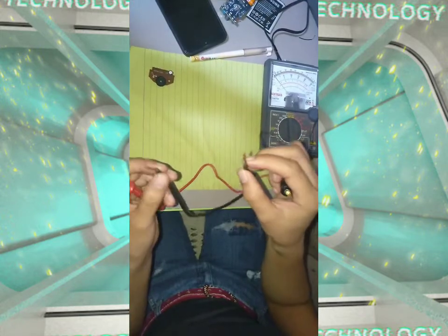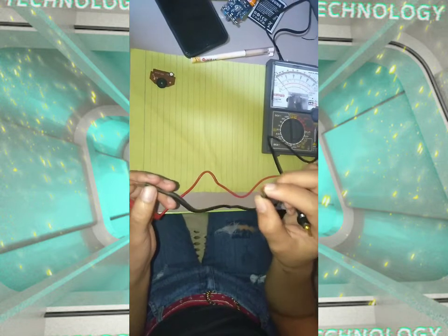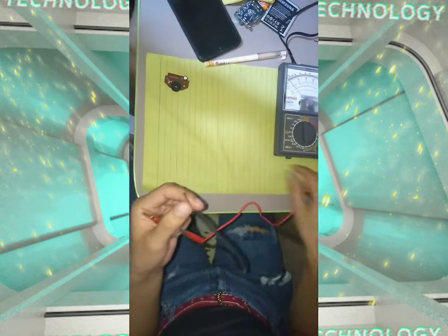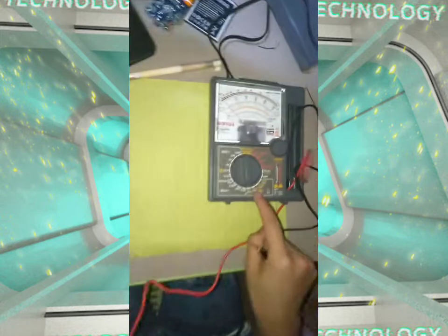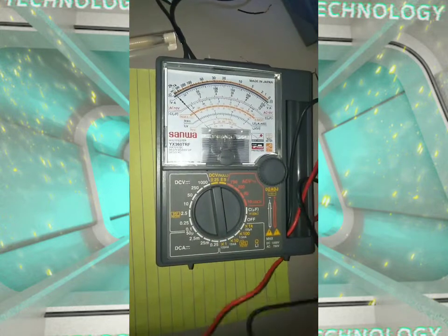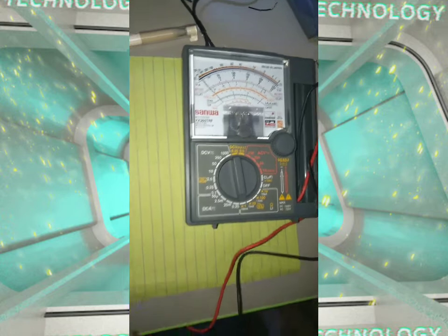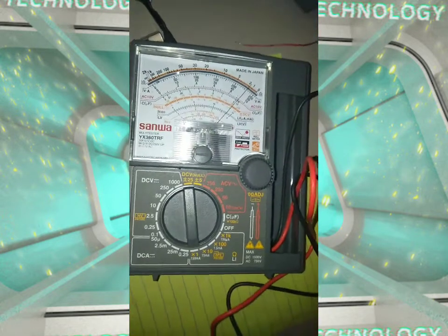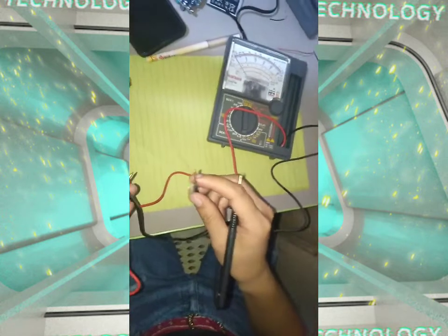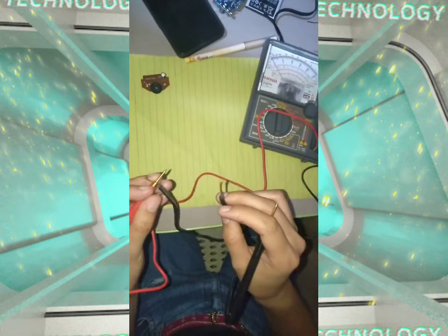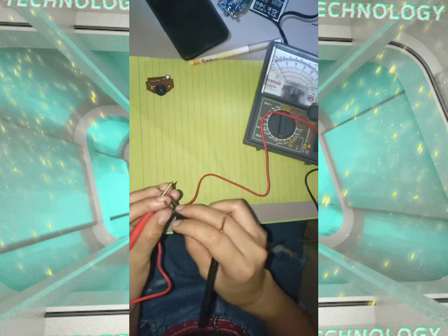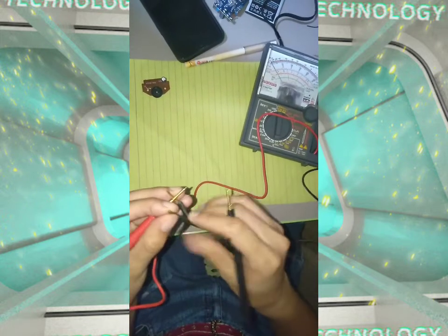I have here another wire, which is the black one. The range of the multi-tester is still at times 1. If we calibrate this one, it is still at 0 ohms. So now we are going to test this wire to see if it has a connection, from here to here.